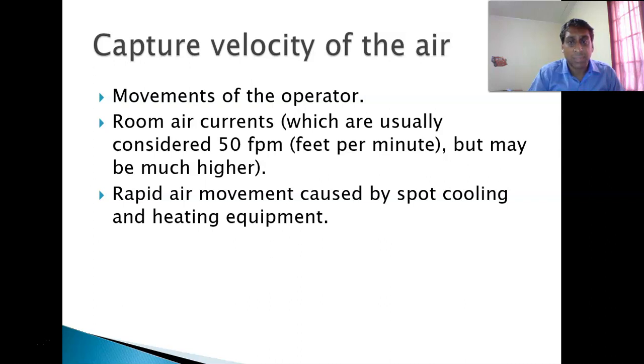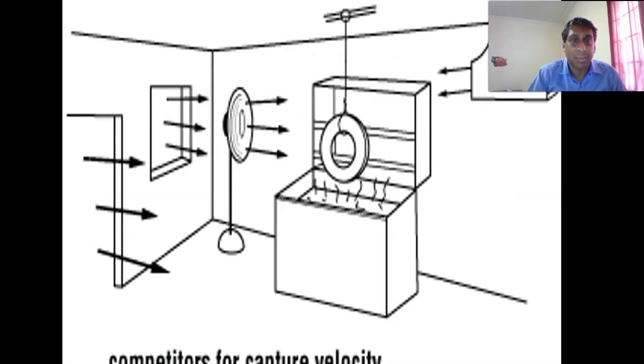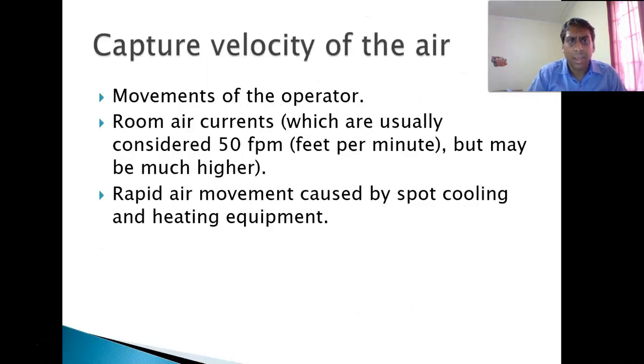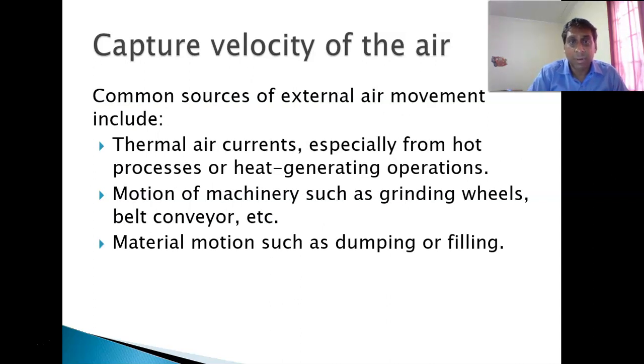So what was this all about? In addition to just talking about capture velocity, this again has come up for exams before. It would have been, what are the competing systems for the capture velocity? Simply saying that the vacuum of the hood, the air pressure that captures, must be great enough to overcome all of these competing movements of air within a room.